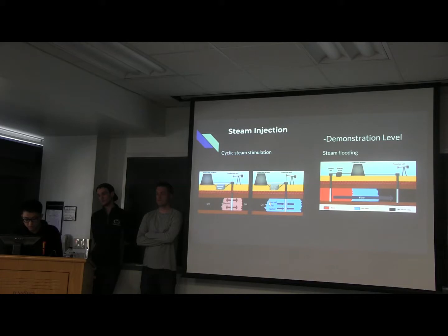After the target viscosity is reached, steam injection stops to allow the heat to redistribute evenly in the formation. This helps maximize the amount of recovery after this stage. The well can then be produced until the temperature in the well drops and the viscosity increases again. After that, a new cycle of steam injection starts to heat up the reservoir.